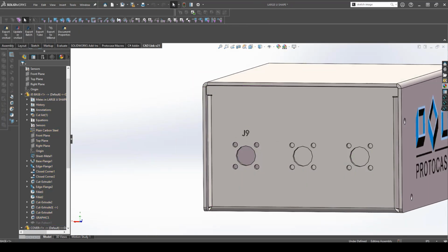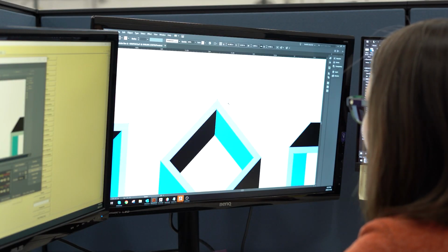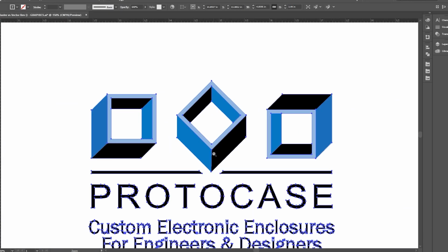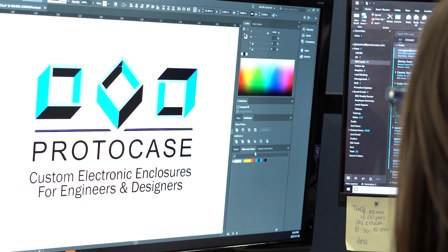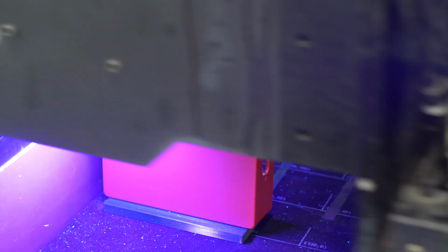Now we do have a few tech tip videos that we've released previously that cover great tips for applying graphics to your design. The recommended way to submit graphics with your SolidWorks model is to use the cut extrude features and DXFs to add the graphic, which gives us full access to the geometry of the graphics with accurate positioning. Now, it is recommended when submitting a graphics file to save it in a vector format and not raster. You'll get the opportunity to approve your models with graphics before your design enters production.